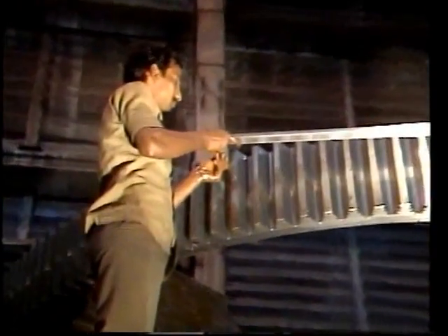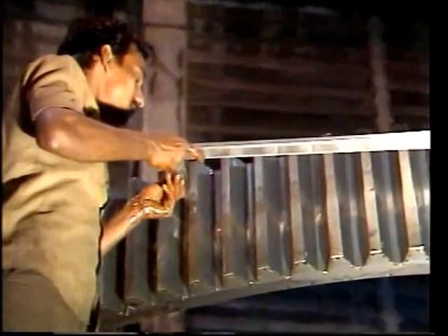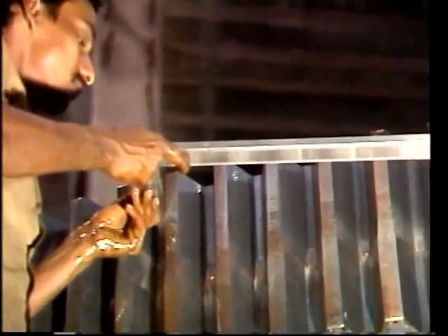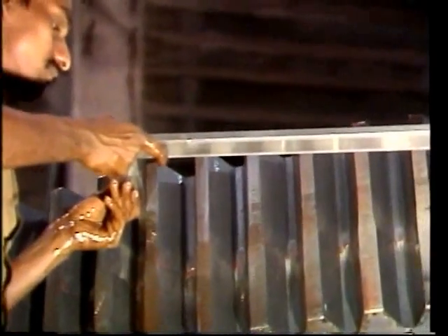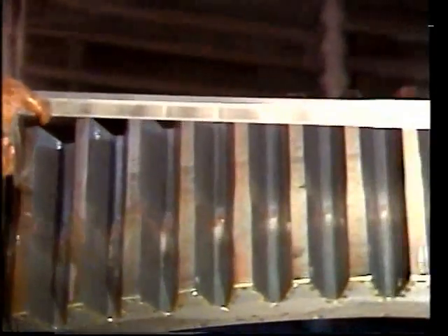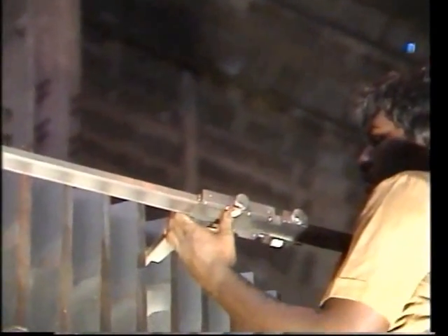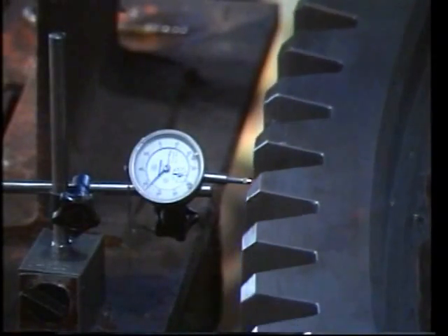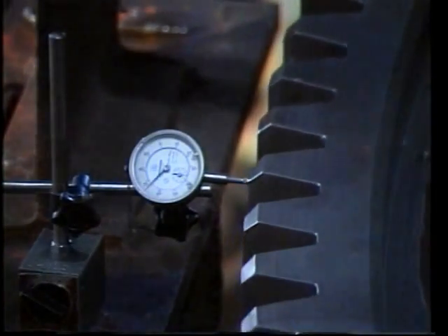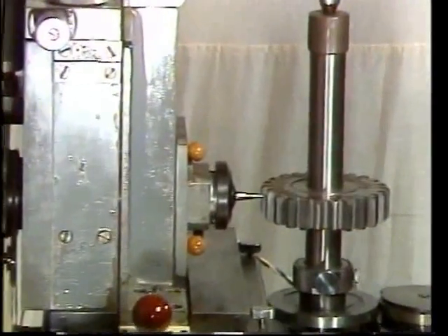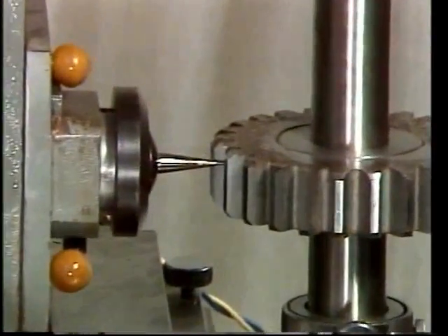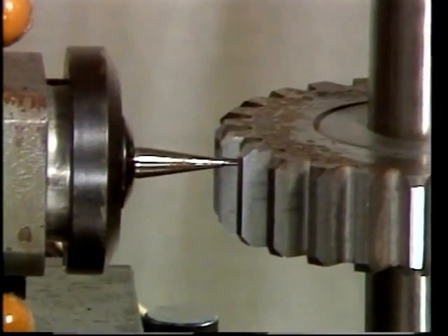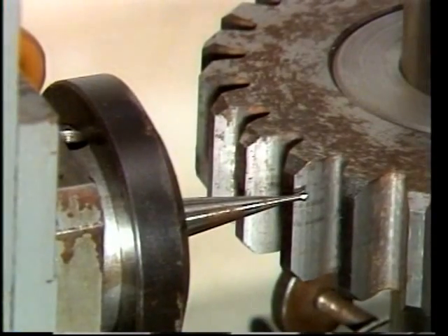The product gear is inspected at various stages of manufacture. Individual elements such as run-out, tooth thickness, depth, pitch, and involute profile of tooth are inspected after the completion of the gears.